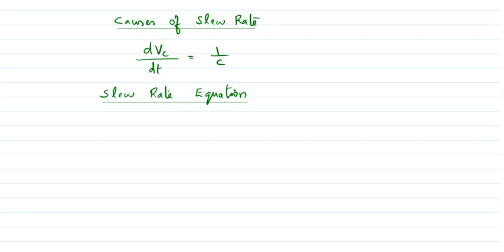So we know V0 will be the input that we applied, so V0 will be equal to V in. We will write the equations for both V in and V0 here. The equation for the sine wave, since we are applying the input as a sine wave, is V in equal to Vp sine omega t, where Vp is the peak voltage. So this is equation 1.